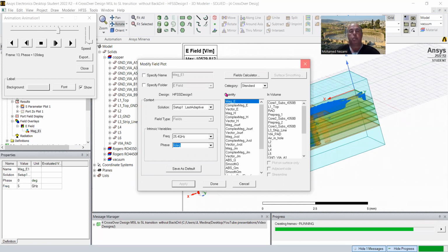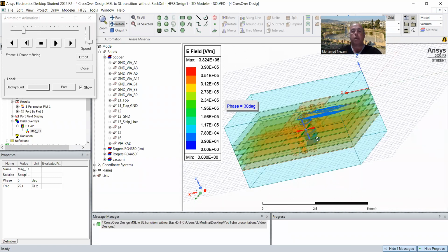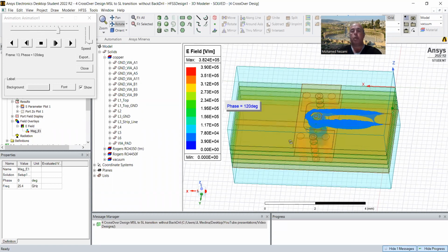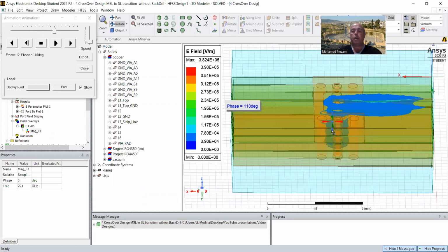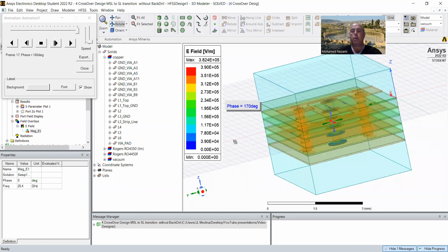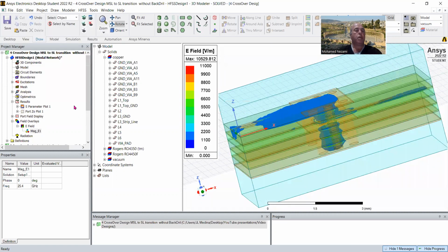becomes a short, because as you know, a parallel open stub, if it's at a quarter wavelength, becomes a short. The quarter wavelength transformer is an inverter, actually. If the load is open, it looks short at the input. And you can see that right now. That's this here.